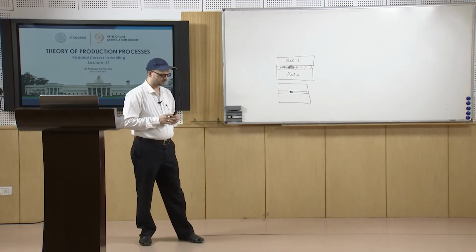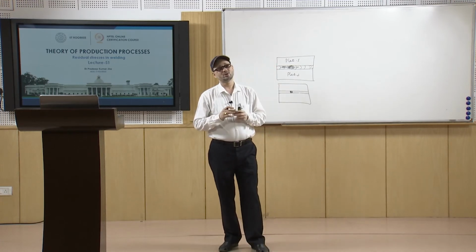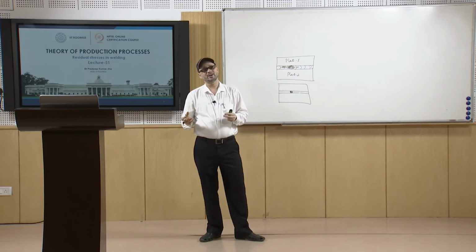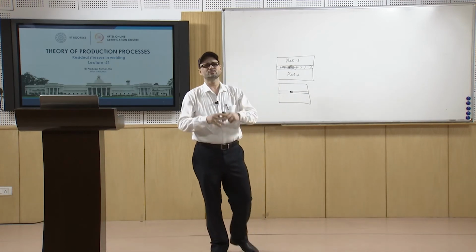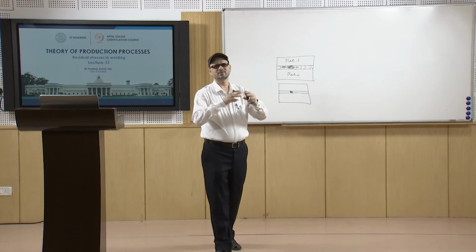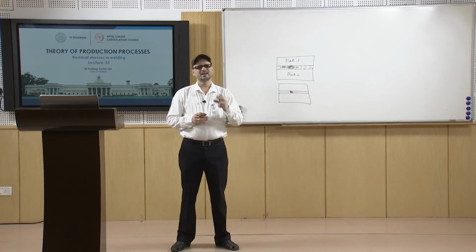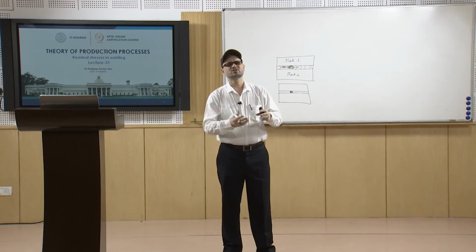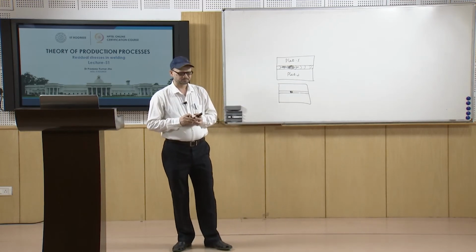Many a times what happens is that when you are taking the welded material out and doing the machining, the stresses may be released from certain points, because we know that it has to be self-balanced in itself. So, many a times we can see that because of the imbalance of stresses or the improper value of stresses at different points, there may be distortion of these welded objects during the machining process itself. So, that job may be out of its shape.